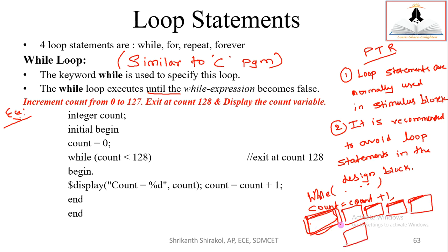If it repeatedly appears, then your hardware consumption becomes too high, and you run out of space to fit your hardware. This is not an optimized design. Maybe it synthesizes if it is within the limit, but it is unoptimized. Hence, always avoid using loop statements in the design block.